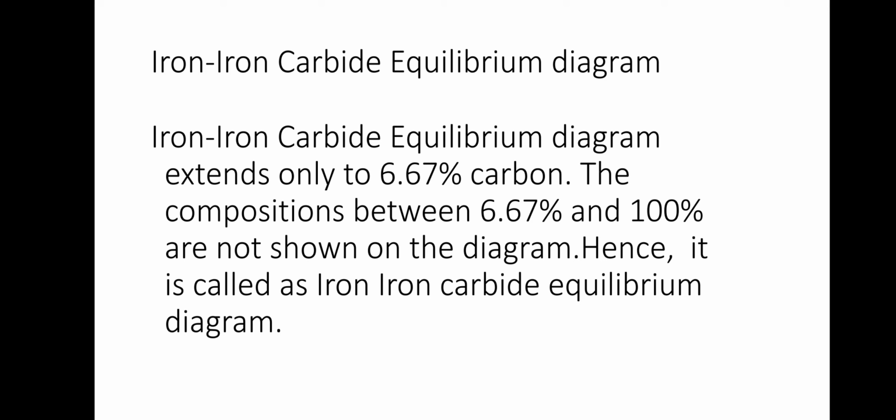Next we will go to the iron carbide equilibrium diagram. This diagram extends up to 6.67% carbon. The compositions between 6.67% and 100% are not shown on the diagram.